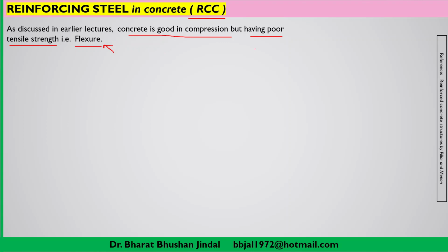So when the loads and forces are acting on the member, it will be under flexure. That means it will be under bending, and when a member is getting bent, then one part of the member will be under compression and the other part will be under tension.